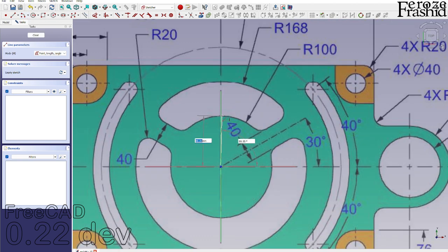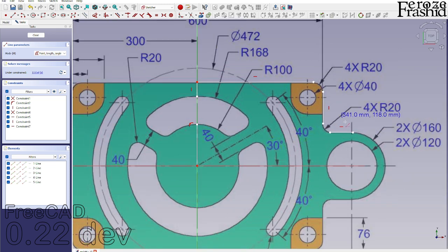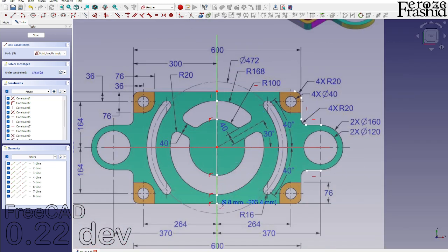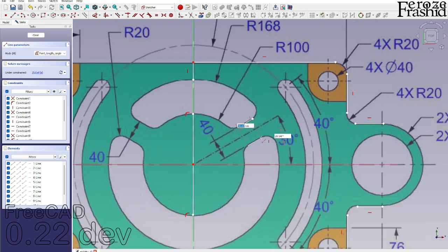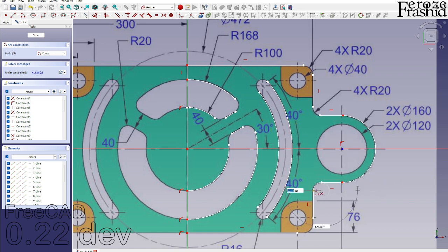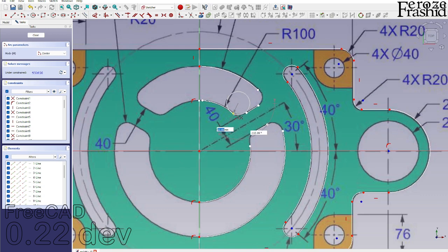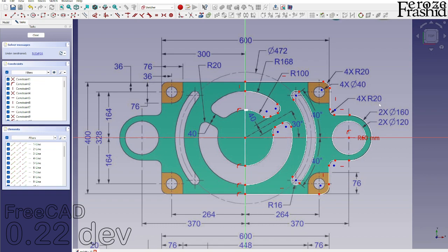It's a developer version. But on this one, looks like I will be using line command and arc a lot without using the polyline. I like polyline, I just don't want to use it in this model. Polyline creates a lot of unnecessary perpendicular constraints automatically, especially after I draw an arc with it. And on this model, I'm just guessing it may be an issue. So we'll just keep it simple.